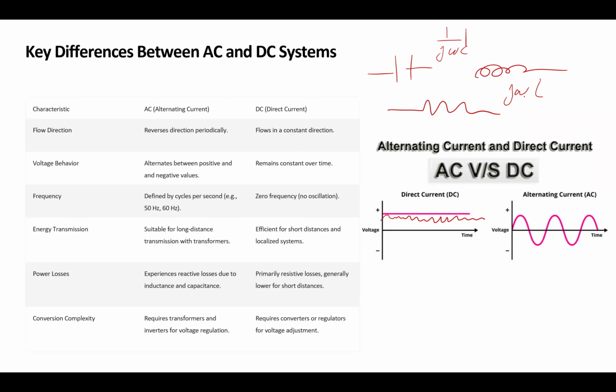Put that next to the concept I mentioned, that a power electronic system introduces not only the fundamental frequency, which is desired, the 60 hertz, but also creates harmonics. So you have one inductor, but it has one impedance at 60 hertz, another impedance at 120 hertz, another at 180 hertz, in the harmonics.